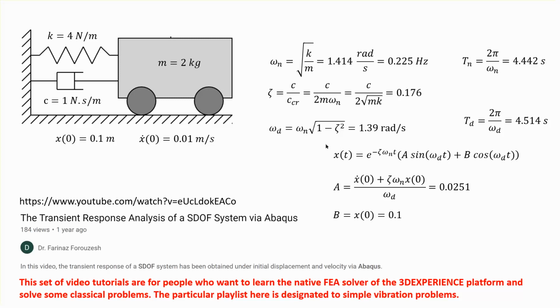The solution to this damped free vibration problem is right here, where all the parameters that you need are known, and the values are given there, and the initial conditions are 0.1 meter. So you move this mass by 0.1 meter in a static step, and then we release it. But when we release it, we also give it an initial velocity of 0.01 meters per second.